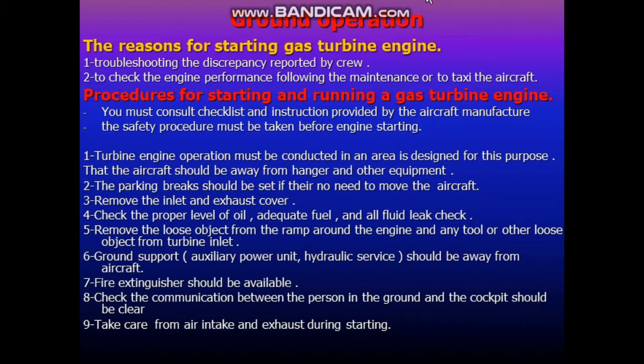The first one, turbine engine operation must be conducted in an area designed for this purpose. So we will not start the engine in a small hangar or near something that will affect the engine. It will be in something like a ramp, where the aircraft should be away from the hangar and other equipment.